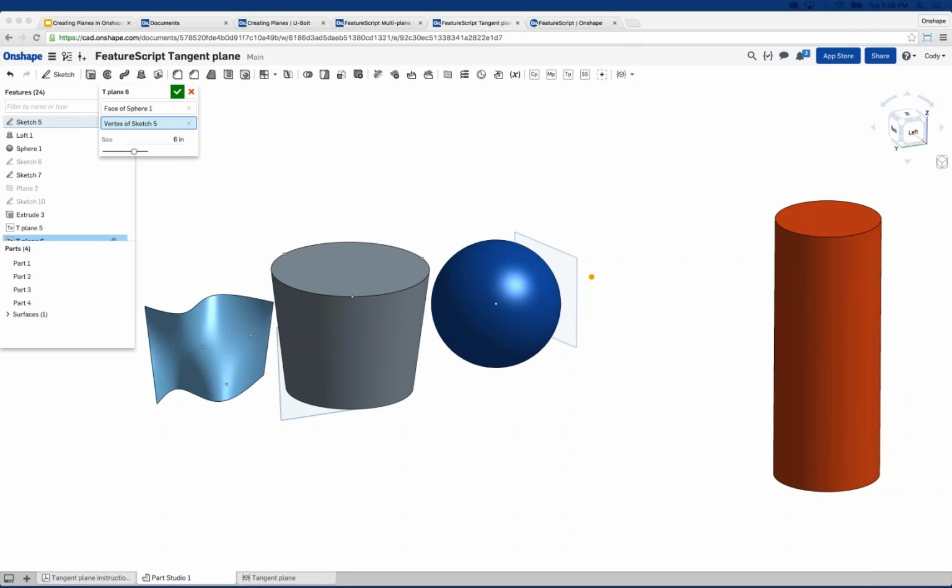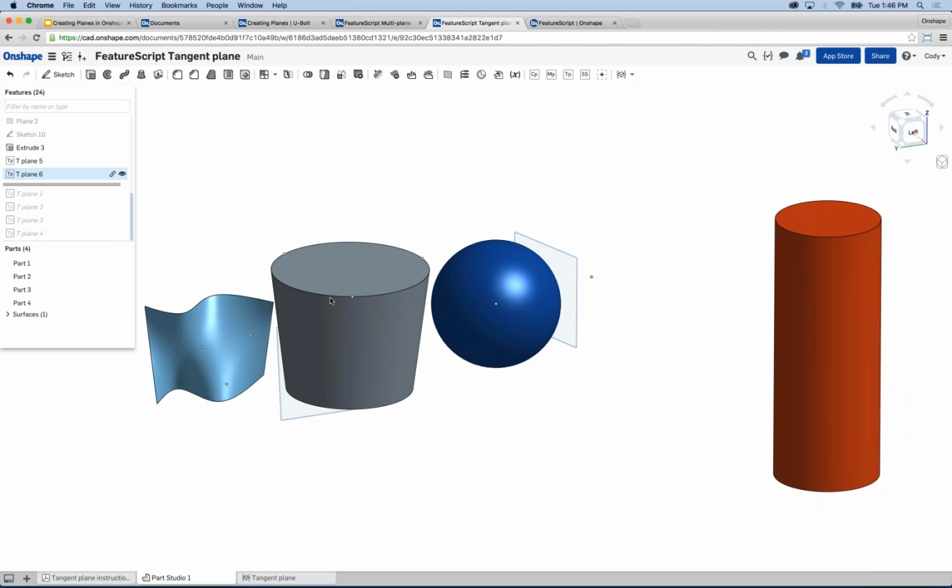Okay. What will happen if I delete one of the planes along that line? The thing to keep in mind about all of these commands is that they are tied to the feature. If you delete the feature, you're deleting all of the instances in the multiplane example. Now, you can't go in and say, I want to delete one instance within the 5 in the multiplane example I was showing you a moment ago. So it doesn't have that level of control.